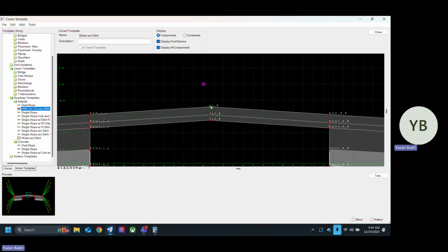So if I have it at an offset, this offset is going to be throughout the whole corridor. It's not going to be at the right profile elevation. It's going to have the horizontal and the vertical offset. So you don't want that. You got to be careful. Here I would have about a 0.6 foot offset from my actual profile. The cross sections will all be wrong if you have this.